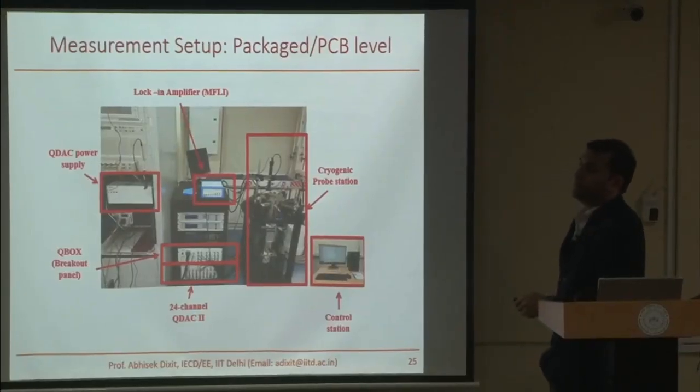Good question, Professor Lagere. Whatever experience we have had with variability, you can typically divide it in two parts. One is static variability, the other is dynamic variability. You combine the two and talk about overall variability, look at the ACLVs and so on. Static variability comes from the fabrication of the device, which is not going to change at cryogenic temperature, right? What is going to change is at operating time, which is the dynamic variability.